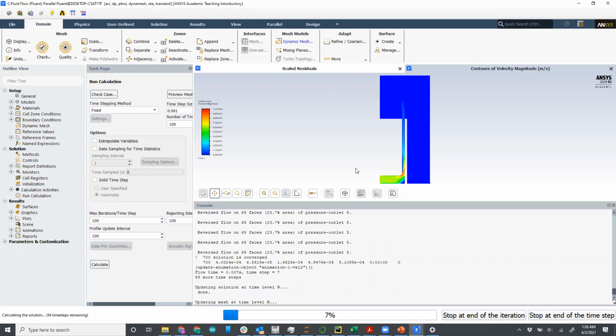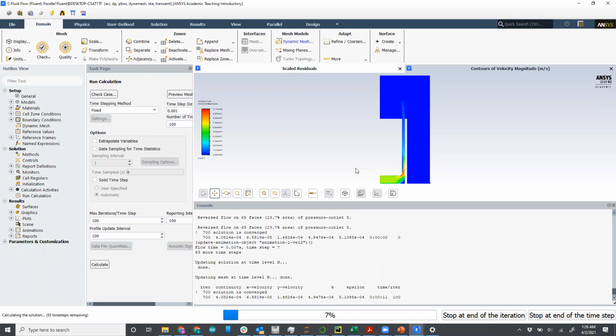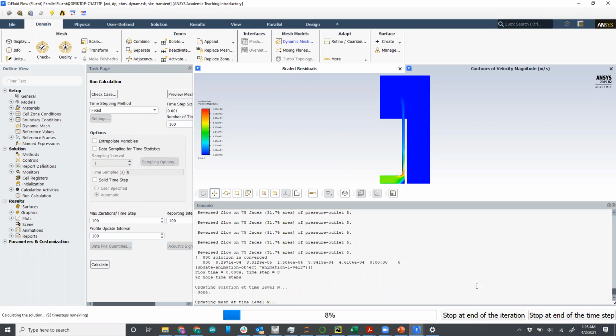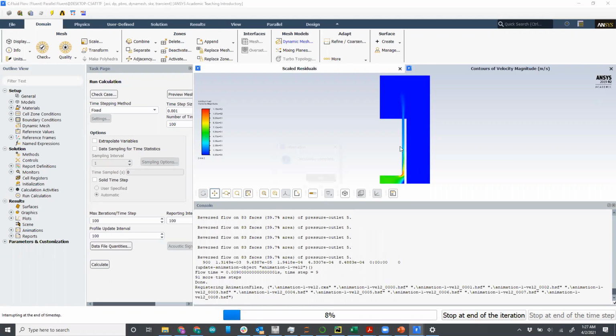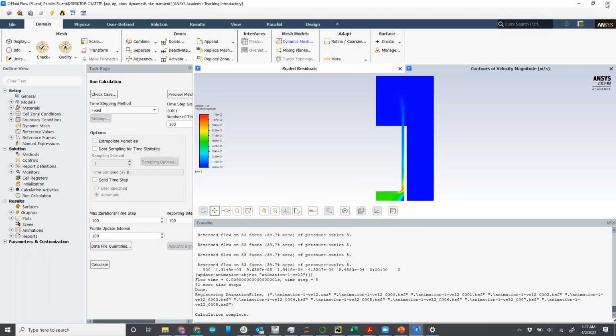And then in order to reset the dynamic mesh, so you end up with the mesh in a different position at the end of the simulation, of course. So we can go ahead and stop this at the end of the next time step. You can see it's sort of starting to get picked up now. Okay. The way to reset it, and this is probably not the best way of doing it, but this is the only way that we found, was to quit.